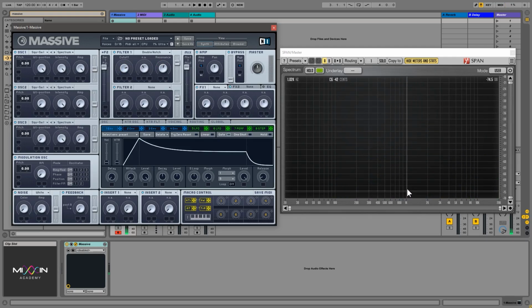So you see that two notches following each other. So two notch filters in series, and we control them both using this. So some special types of filters, which are actually combinations of those basic ones. Now you can find these types of filters in many equalizers as a collection of filters that actually comprise one equalizer that controls the spectrum response of the sound.